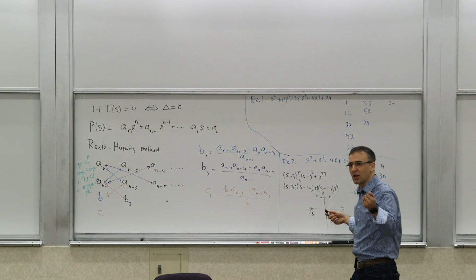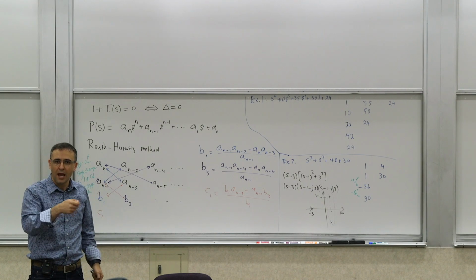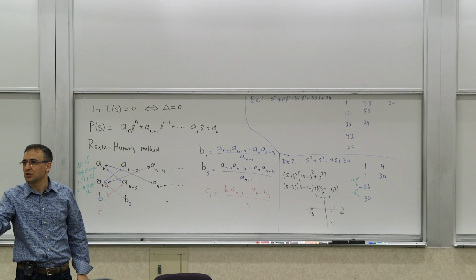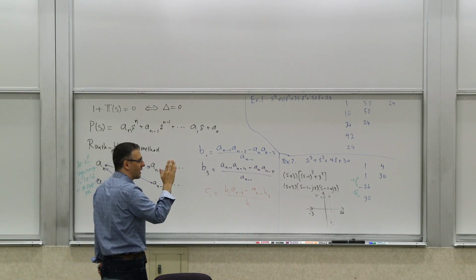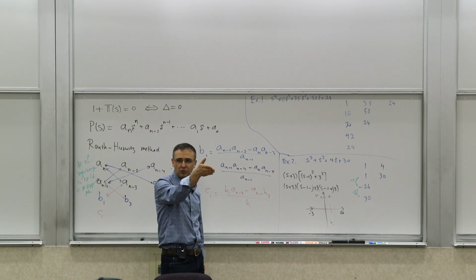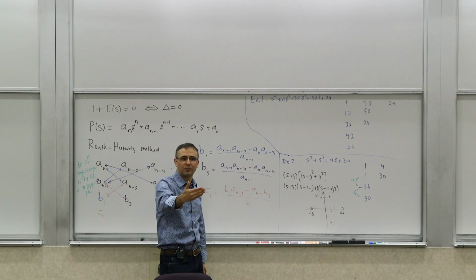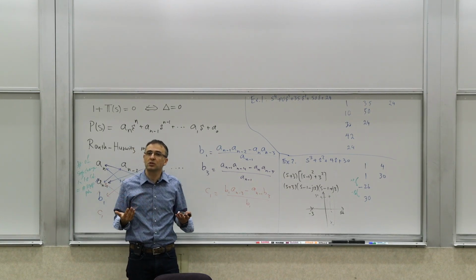You can apply a sinusoid to the input and change its frequency, and the amplitude and phase of what comes out changes. You can plot that versus frequency, and that's a Bode plot. You can plot the magnitude of the ratio of the output to the input, and the phase of the output sinusoid relative to the input sinusoid, versus frequency.